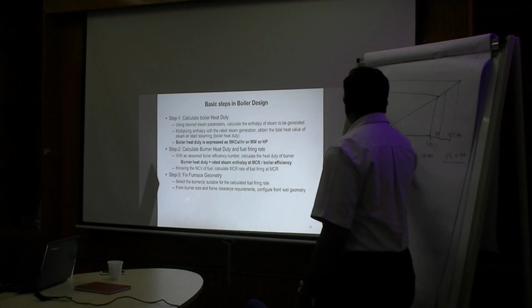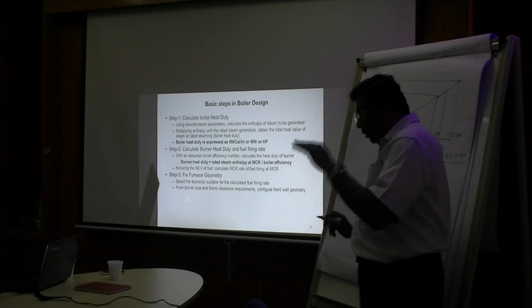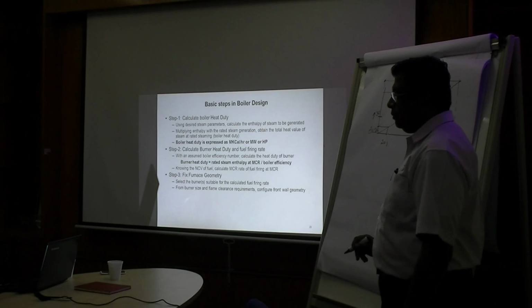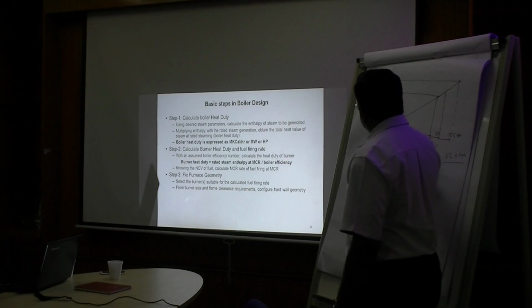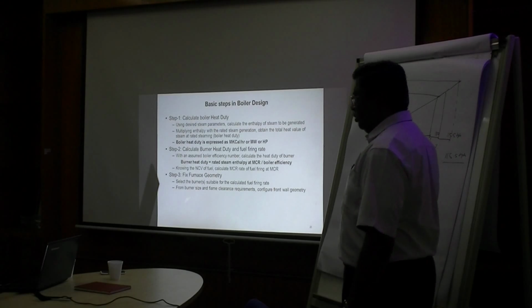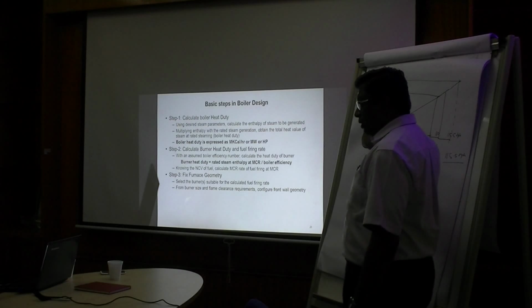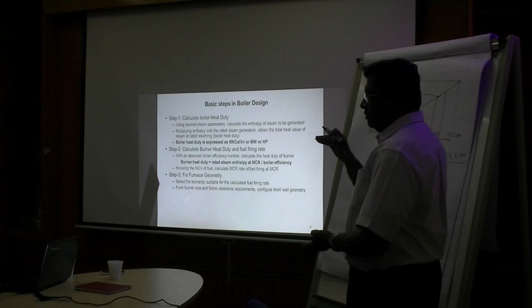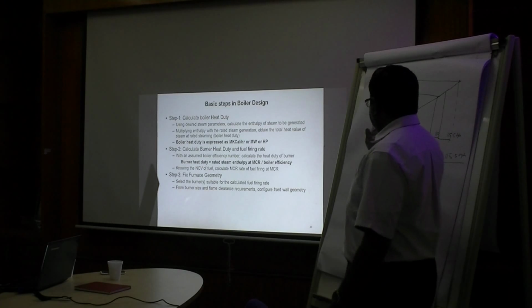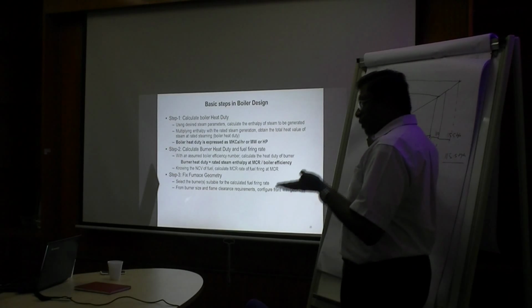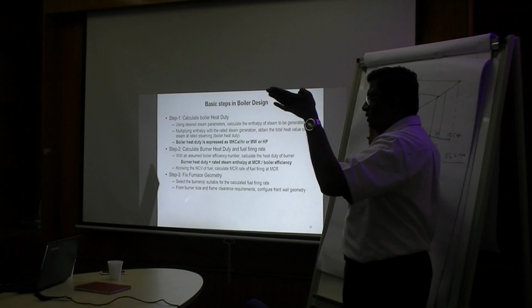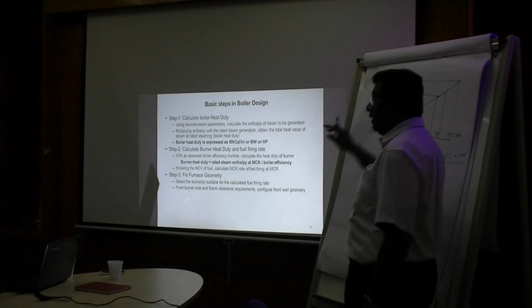Okay, let's call it 30. So if you try to go below 30 tons, the burner may trip. So how to bridge this? How to make sure that 20 ton is within the turn down of the burner? That means this 20 figure should be 25% of something. How will you get that? Only if the burner is rated for 80 tons.